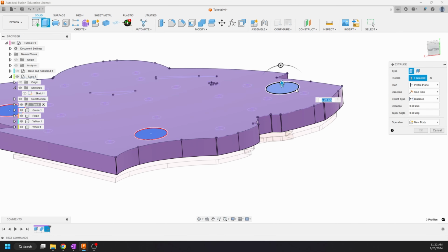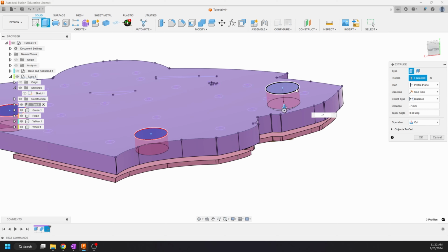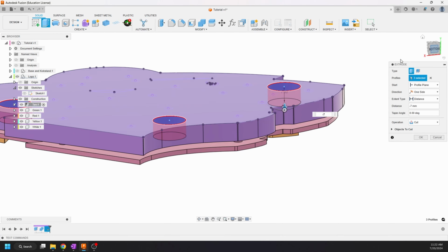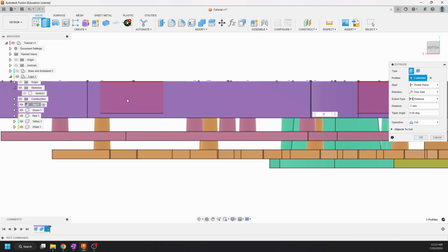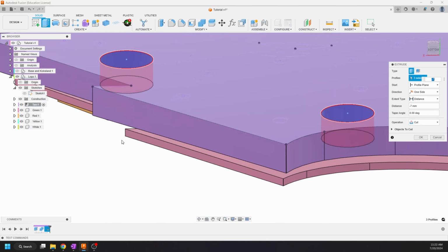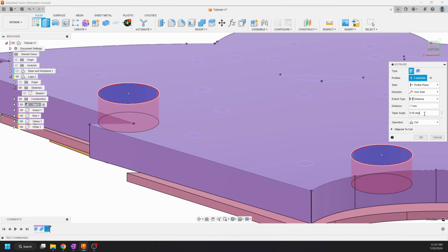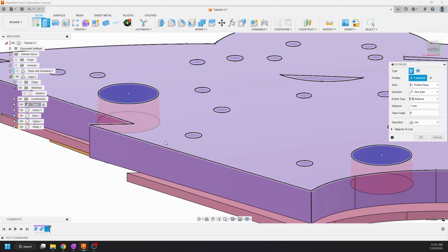And I extrude these 7 minus 7 millimeters. So almost the full distance. Only do that because the TPU inserts that I designed are that size. And I put a positive 2-degree taper angle. You can see that flares out the inside a bit. That way when we install the TPU adapter, it's almost a mechanical retention since it's flared out. The TPU is flexible enough to get it installed, but once it's in there, it's really hard to take out because it has that 2-degree taper.